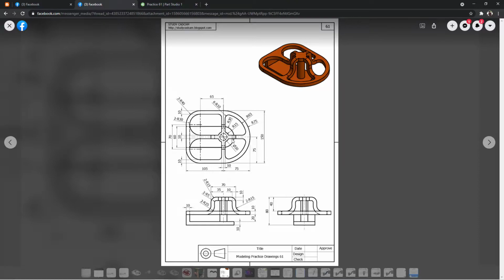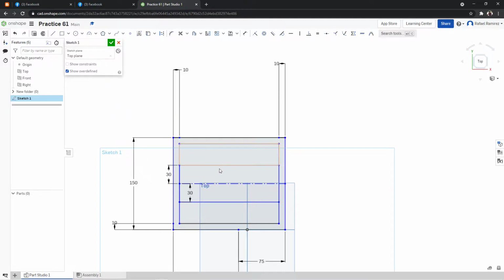And then the end point, this semicircle, is actually based on the center and has a radius of 30. And the end point, if we are only basing it on the rectangle, this one towards that one, it intersects with this line at the center of our figure. So in order to do so, at the 75 millimeter horizontal length, this one, we'll put a line here, and then this is going to be our rectangular shape, just like that.